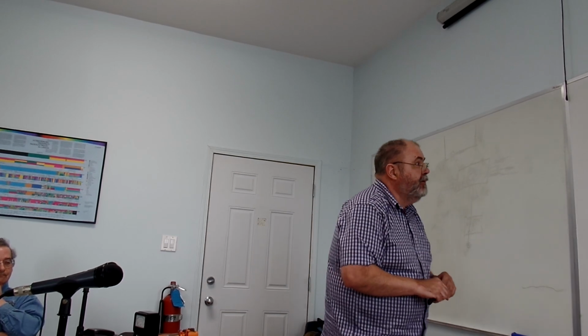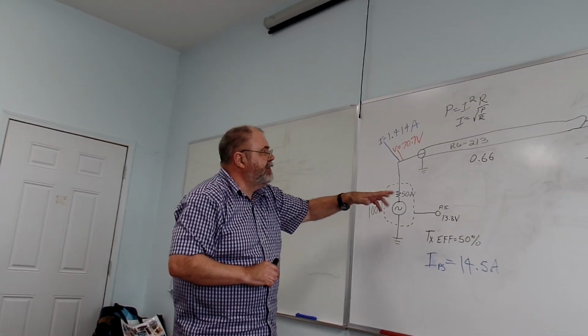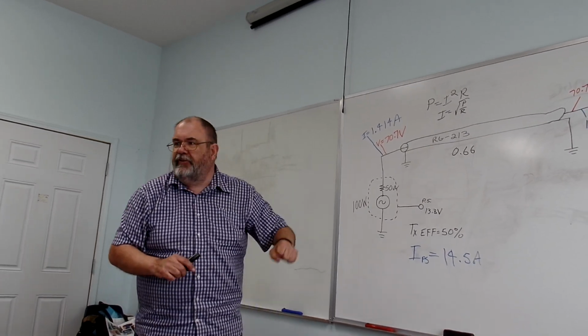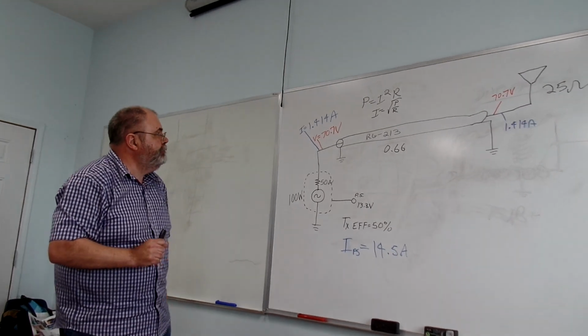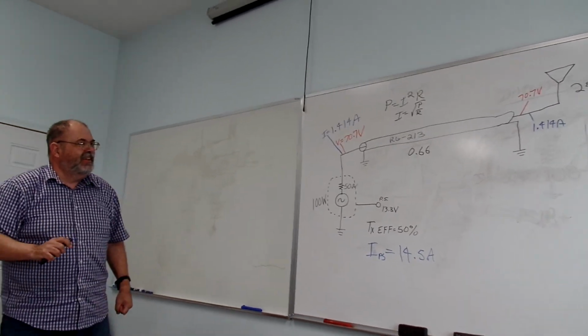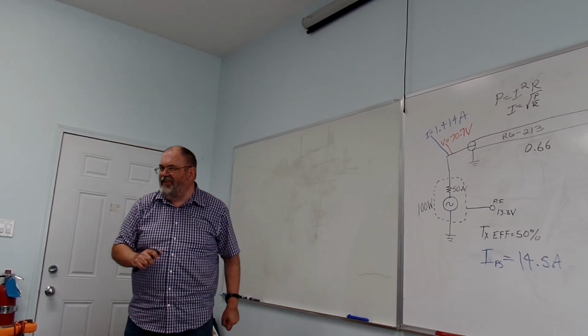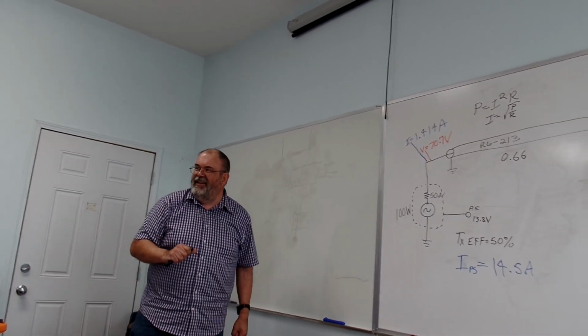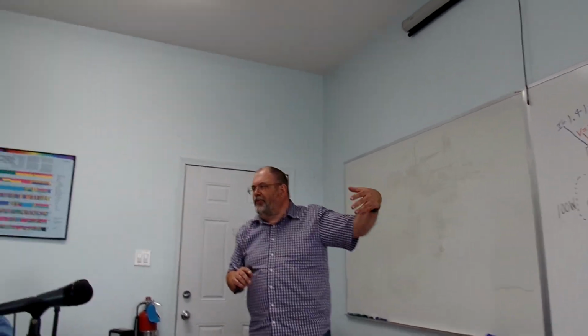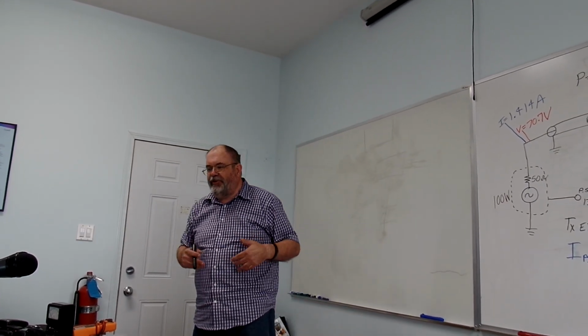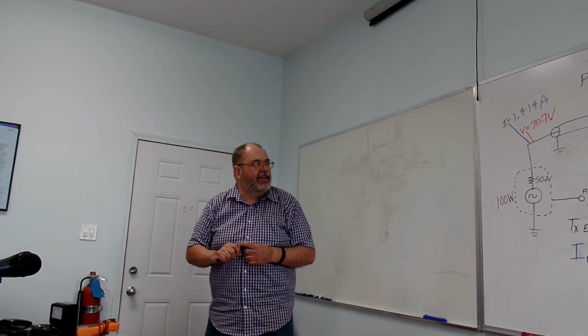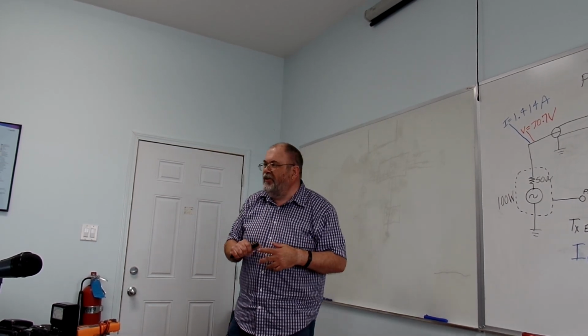So, with all these numbers being said, and velocity factor of RG213 being 0.66, hint hint, it is on the test. It seems to be one of their favorite ones. Yeah. Well, the RG213, the polyethylene coax, that's by far the most common. RG213, RG58 has polyethylene, 0.66.